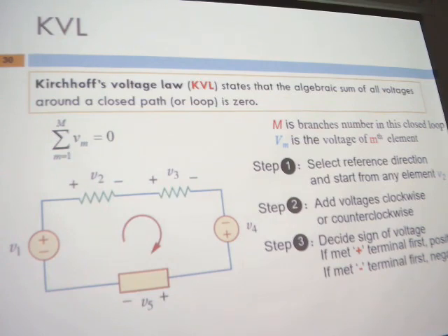Yes, for passive element we use passive convention. For active element we use active convention. Remember? Okay, remember it by heart. But you should notice if the direction is given, you have to follow its direction. Okay, if it's not given, we use the active or passive convention by ourselves.